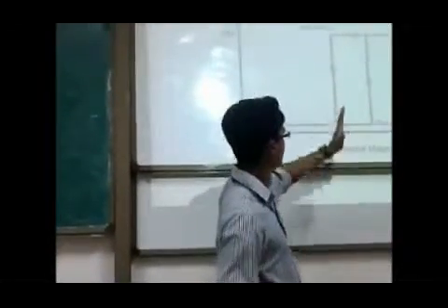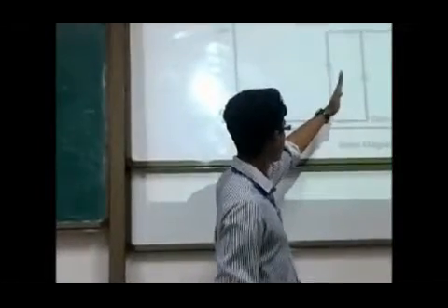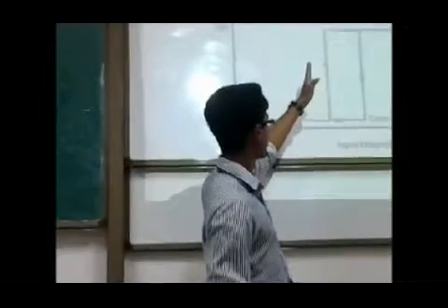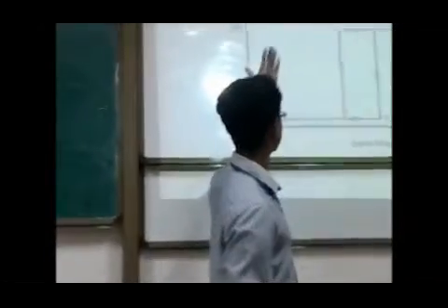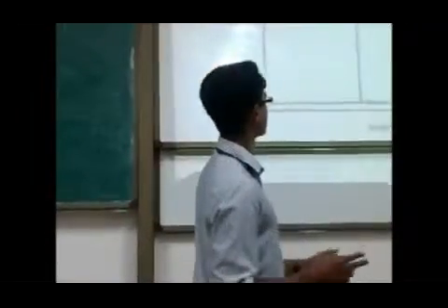Now we can decrease the field to just below the operating point, and after that a point known as the release point will be reached. At that stage the sensor will switch back from on state to off state. That's the exact working of a digital feedback sensor.